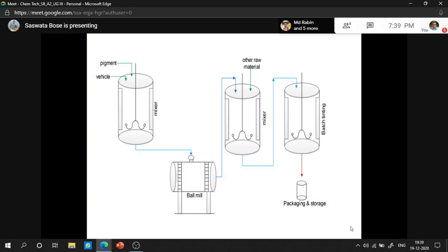Okay, in the second step, you are adding the additives to get the paint out in the final step. So the speed of mixing is very important in the second step. Then before it is packed and stored, a few tests have been performed. That is very important: the viscosity test and the degree of dispersion test. Those are carried out with the finished paint.